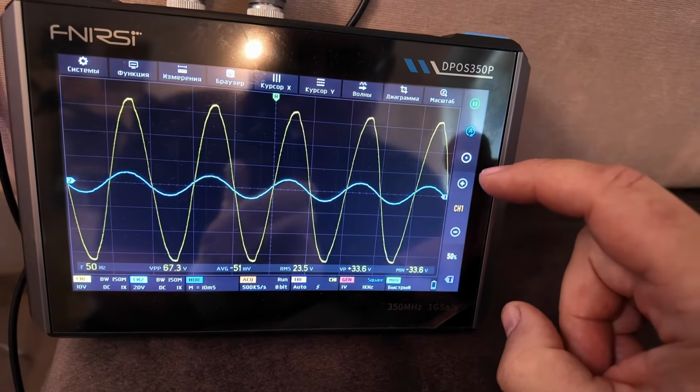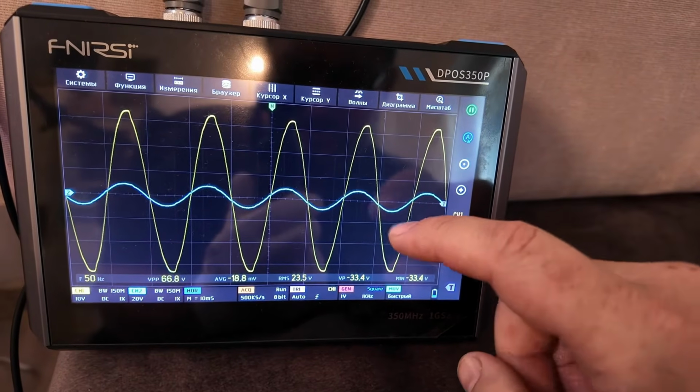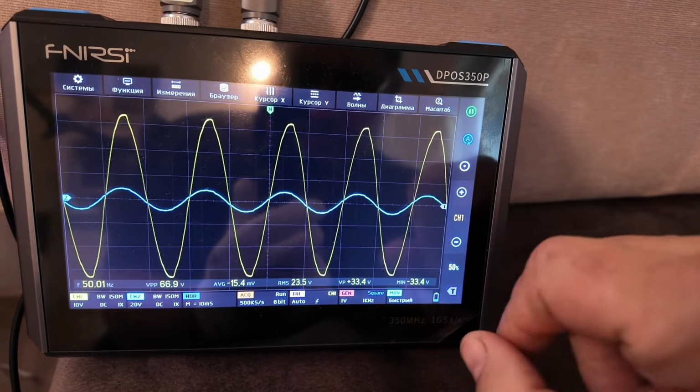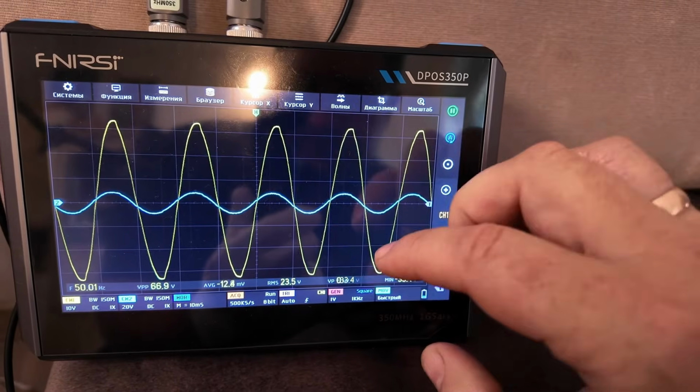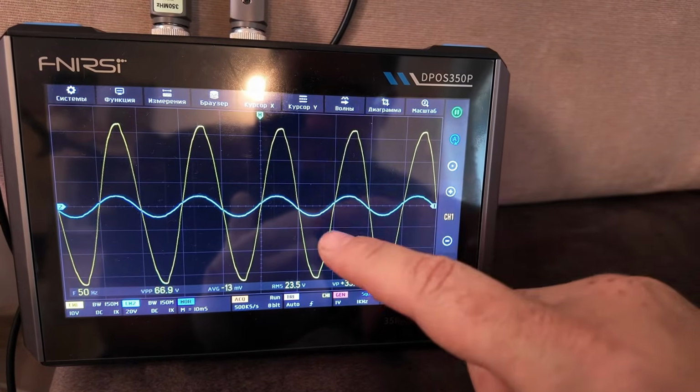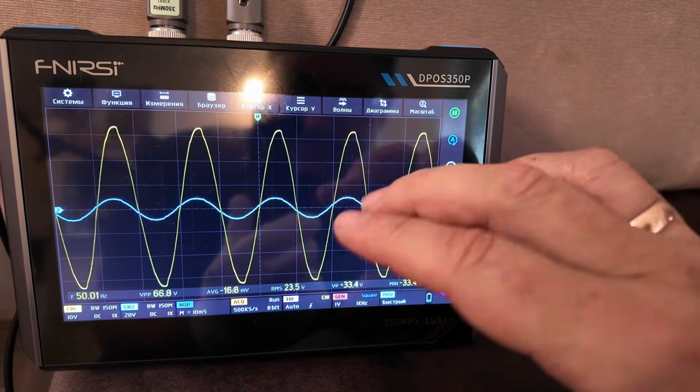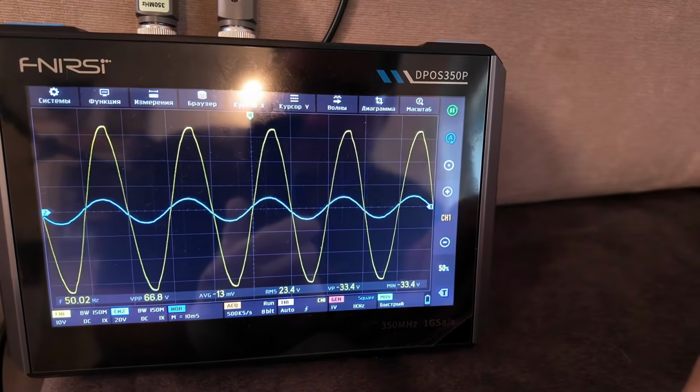And we can see that our signals are not in phase. There's a phase shift. This means the phantom has some reactive nature. But the shift isn't 90 degrees. It's different from 90 degrees because there's also active resistance in the circuit. The phantom is very small.